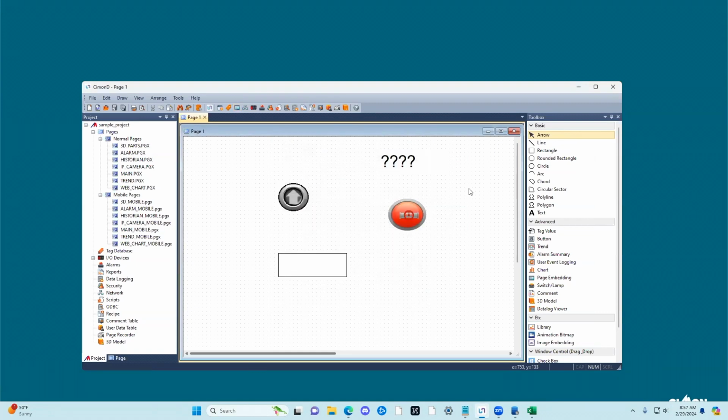So some other things. Now the new SCADA software supports 3D objects. That's right. We support rotating objects in a 3-dimensional manner. So Z, X, and Y. You can attach tags to certain aspects of the 3D object. So maybe it's a building and a part of the building caught on fire. You can attach an alarm to that part of the building and a fire. You can create a little fire image that shows up, and it can be a very descriptive 3D model.